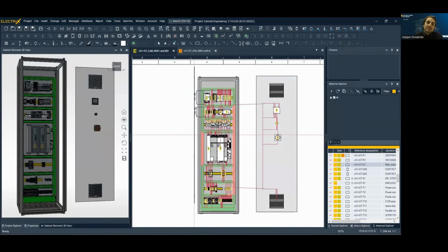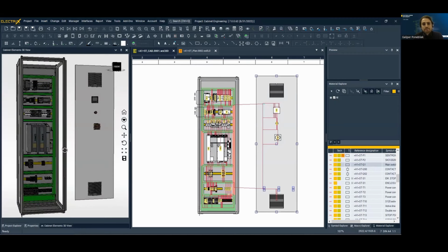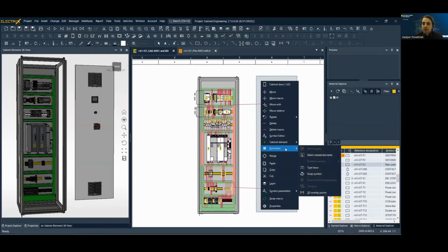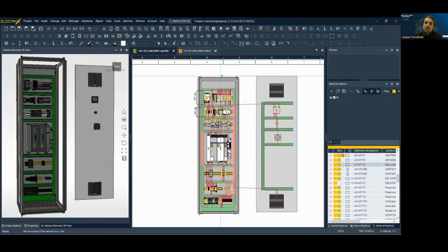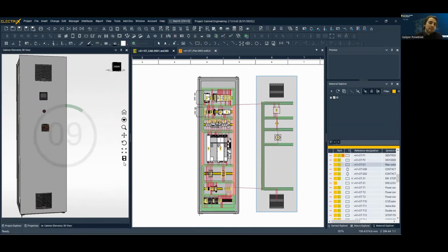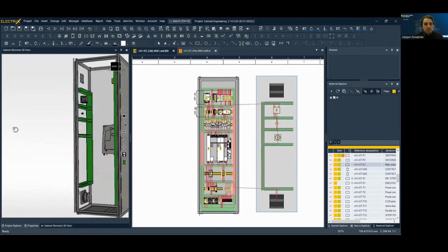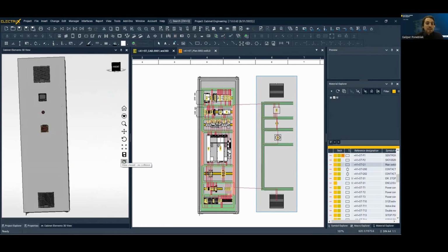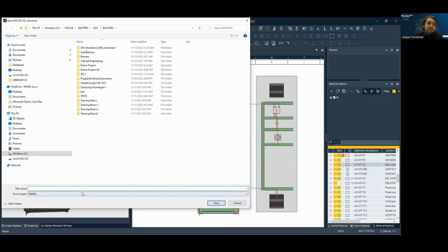So now we can insert this side door, side wall, and check it again in our 3D model. And we also have the collision check. If we close this door, the collision check will warn us if the part is not placed right. If there is a collision, the part in collision will be colored red. So we can check it like this. We can check this 3D model again, and we can see that everything is fine in our case. So we can save this 3D model to mesh with material, STL file, and so on.